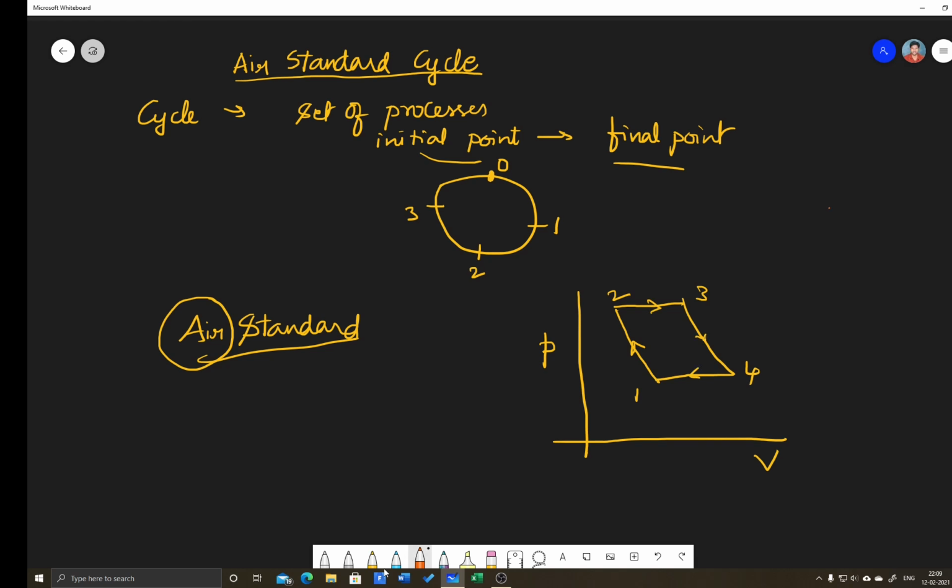There is a cylinder with a piston inside. So process 1 to 2 is compression, that is it has to undergo from this to this. There will be a movement. So compression takes place because the volume is reducing by this much. So volume decreases and pressure increases.